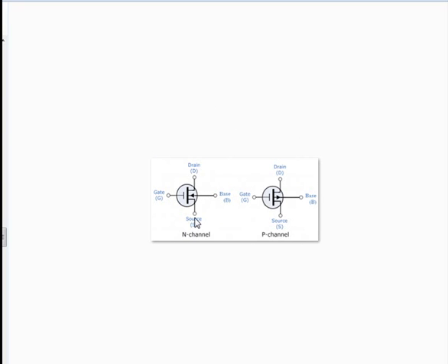If it shows low resistance, it is okay. In the reverse, it should show very high resistance. But if in both cases the value is the same, or it shows a very low value, then it is shorted. That means gate to source is shorted, and it has gone bad or defective.